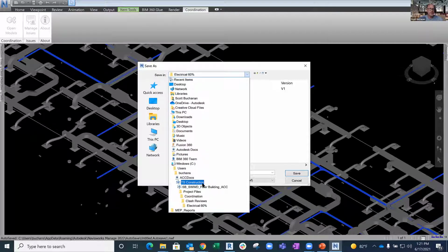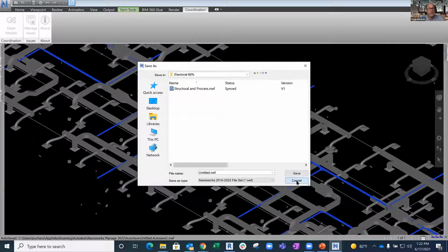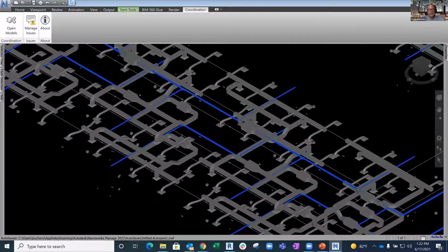If you have active clashes inside of Navisworks, when you rerun that test, it will change all those clashes to resolved for you. Okay, so they're going to be sitting as active or assigned or whatever you put in your normal Navisworks clashing, but that will actually work, which is what like Glue would do as well. And model coordination wouldn't do that until I think like the beginning of the year or maybe late last year, we added that functionality. So this is your Navis workflow. Keep it. All the amazing things inside of Navisworks, do them here. If you need to append other models that are not sitting inside of BIM360, let's say they're using AutoSprink or something like that and sending you CAD files or just NWC files from that, then you can just do your normal append and get those incorporated to it.